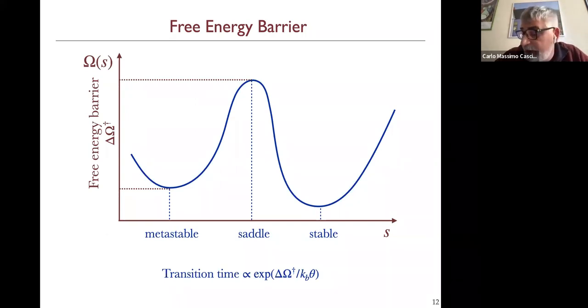And from that you can determine the transition probability. From the transition probability, by changing the thermodynamic condition of the system, you can identify the condition for which the probability of observing the transition is 1/2. And from that, you extract the cavitation pressure.